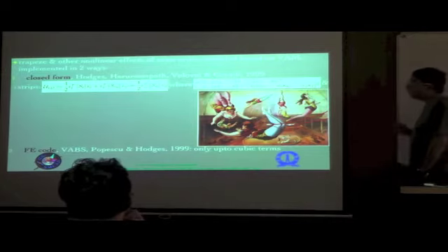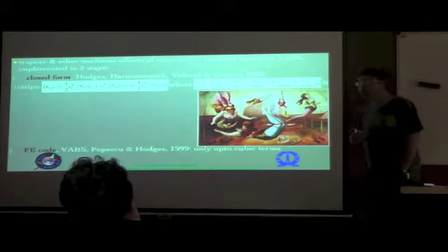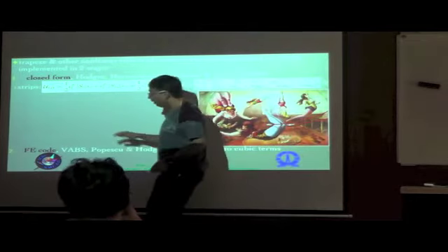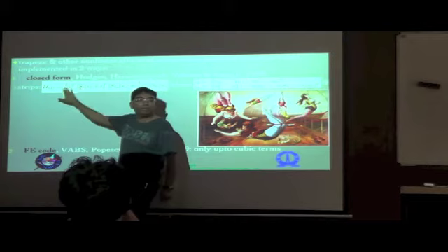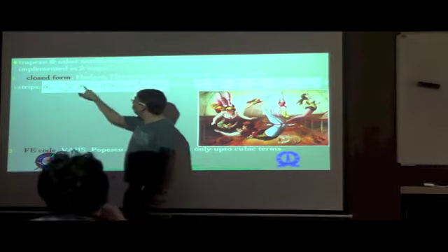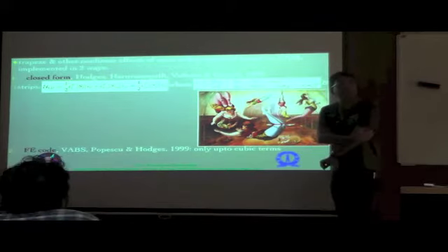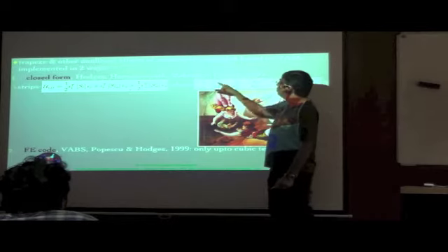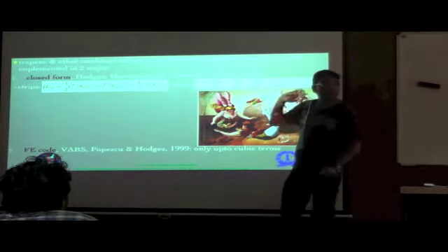To give you a sample, for strips, that is, thin rectangular cross sections, if you didn't have any nonlinearity in the cross section, the one-dimensional strain energy density would have just contained this first term here alone, where you have a 4x4 matrix SN, which is what we've been talking about as S11 bar to S44 bar earlier. Each one of those terms is associated with gamma 11 bar, kappa 1 bar, kappa 2 bar, and kappa 3 bar.